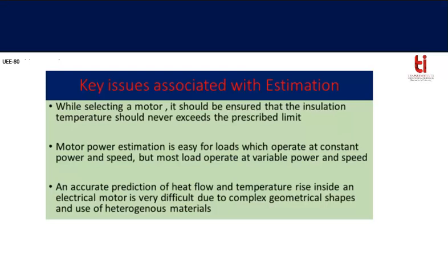Let's discuss the first point with the help of an example. Suppose we are going to select a motor. Now the motor is connected to a load. There may be the case that load torque requirement is more than the torque developed by the motor. In that case, motor will try to cope up with that load. Then motor will draw more amount of current from the source. Because of that current, I square R loss will be there in the motor. Then temperature of the motor will increase.